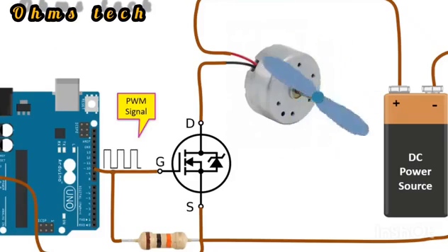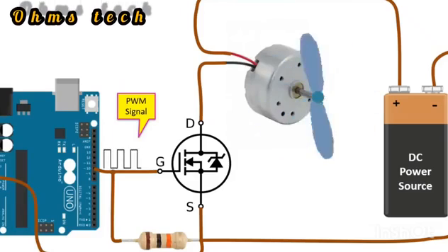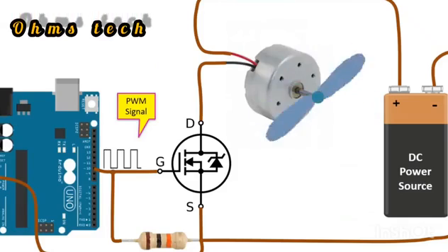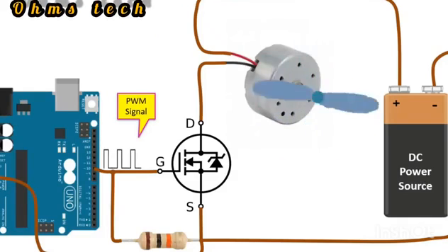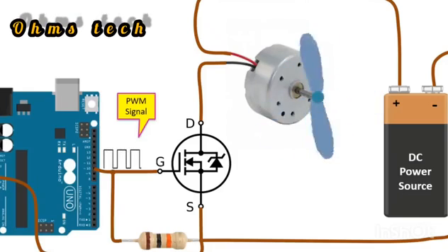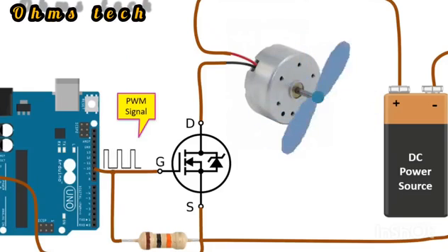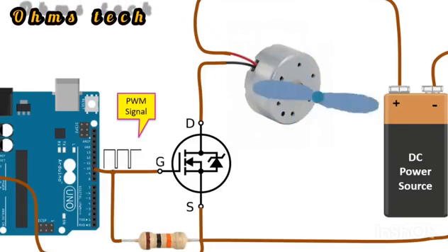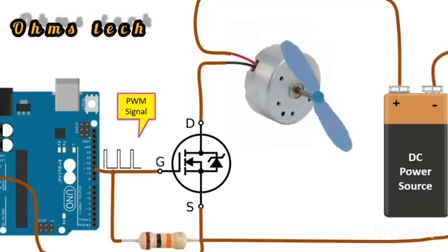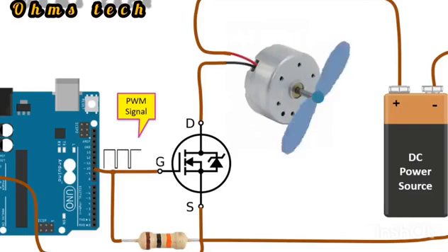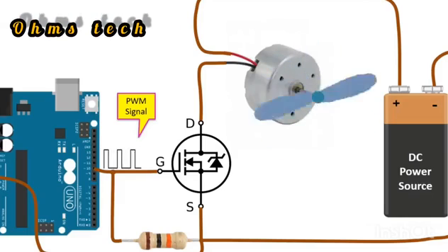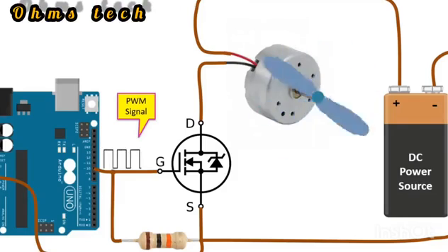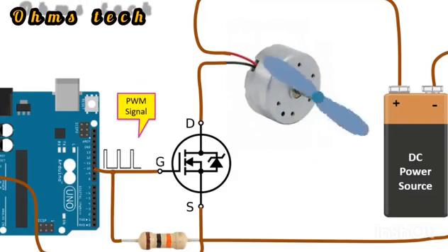With MOSFET, we can control the speed of a motor not only with a potentiometer, but also with a microcontroller, as here. Since the resistance value on the gate pin of the MOSFET transistors is very large, there is no current flow. That is, the trigger part and the part connected to the load are isolated from each other. As such, MOSFET can be easily used with a microcontroller such as Arduino.